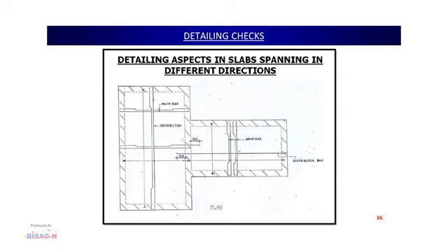We provide the main reinforcement at the bottom, as I already explained in the earlier slide. But what does the bar binder do? They continue this bar into this one as a bottom bar. When this bar is continued inside this span, it should actually become the distribution steel for this slab. But when it is taken at the bottom, again it is defeating the sole purpose.